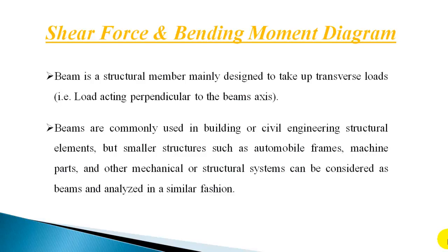To start with, what is a beam? It is a structural member mainly designed to take up transverse loads, whereas a column is designed to take up axial compressive loads. Beams, on the other hand, will support transverse loads on their axis. So the forces will be acting perpendicular to the axis. Some small components may come along the axis, but mainly it will be subjected to transverse loads.